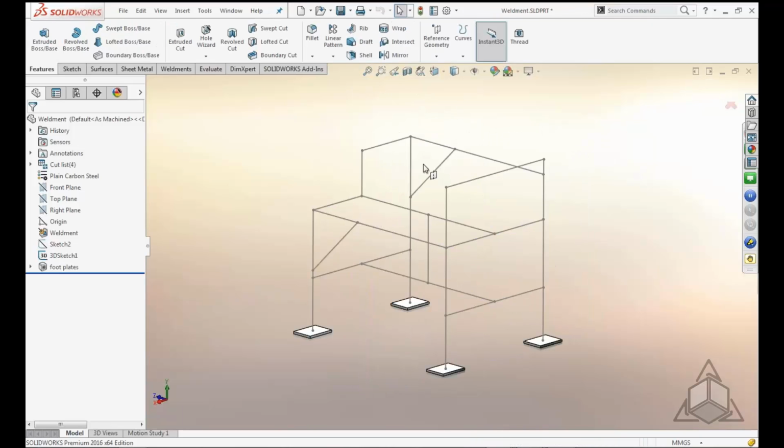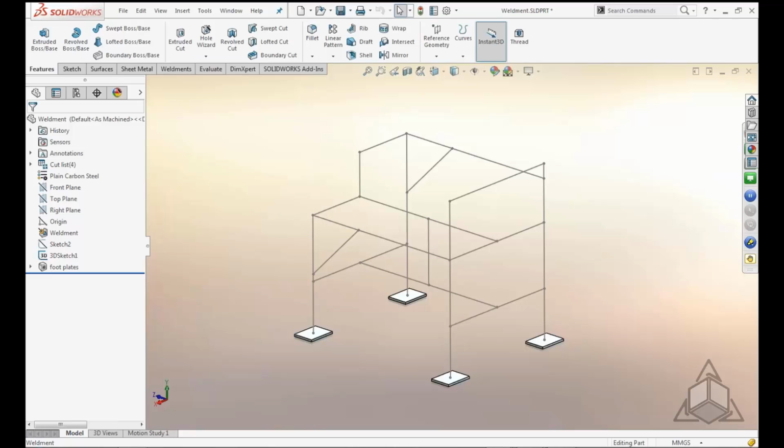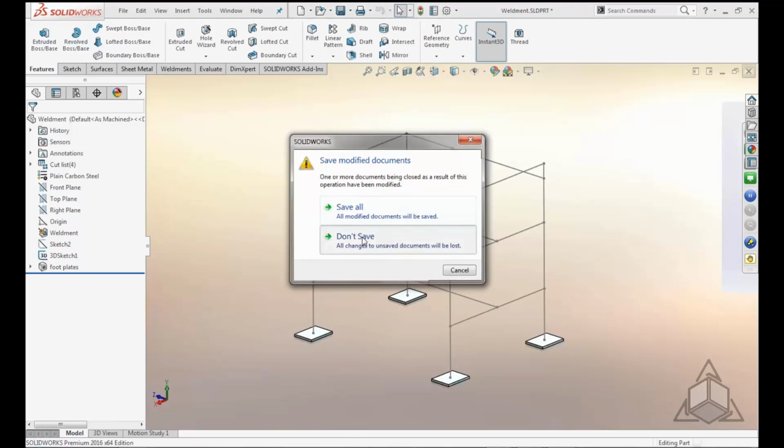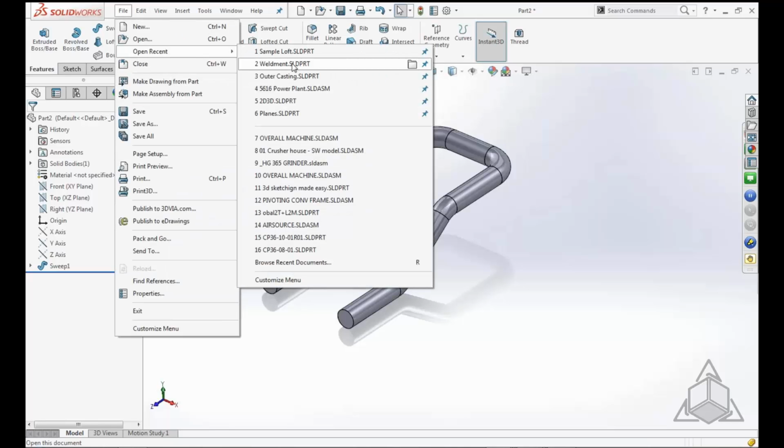And this will allow me to create a proper frame in 3D space instead of 2D. So much less on the number of sketches needed to do that. If I were to try to do this on 2D sketches, I would need at least one 2D sketch for this side, one for that side, one for the back, one for this middle section. I would need 4 different sketches essentially that are related together. And so it takes a few more sketches to manage, but in this particular case, you can do it a little bit faster. A couple other examples.